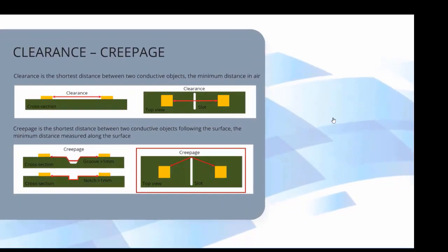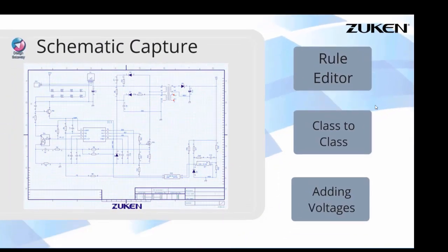So just to give a little difference between clearance and creepage. Clearance is what you see across the air, and creepage is the distance you see across the surface. So clearance is shown here, the slot doesn't matter, whereas the creepage goes across the slot or even through the barrel of a hole, even to the underside, to check the shortest gap between one and another.